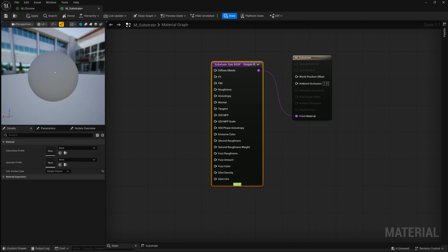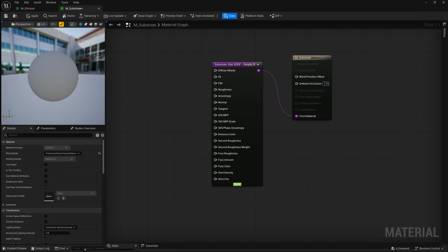Now this doesn't look like glass just yet because there are a few more parameters we'll have to change. One of the other things we're going to adjust is, we'll notice here it says refraction disabled. We need refraction on our glass material for it to distort the background behind it correctly. If you look through glass or you look through water, the background becomes distorted.